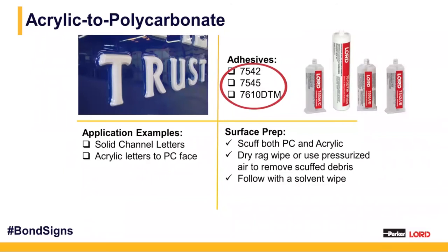The 7542 has a lower viscosity, which makes it a lot easier to flow into smaller parts or tighter tolerances. And it also has that 746 approval. The 7545 is higher in viscosity and feels more like a toothpaste, but it has a much wider variety of cure rates, which is what makes that product popular. The tensile strength between them is nearly identical.